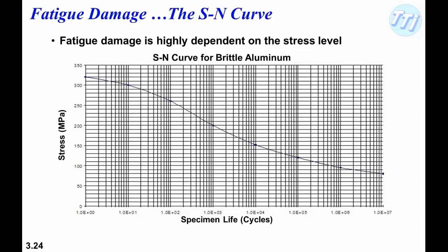The objective was to keep cycling it so that it had a whole lot more cycles than the fleet airplanes, so that a failure would be spotted before the fleet airplanes got that number of cycles.